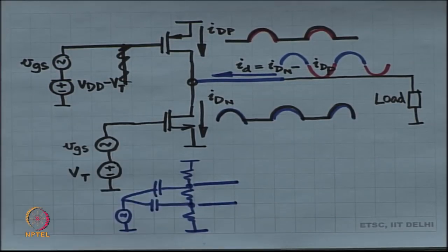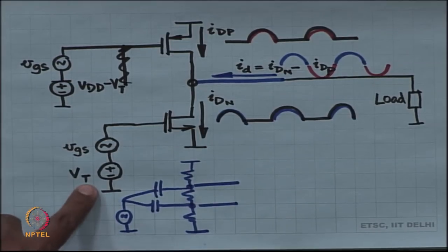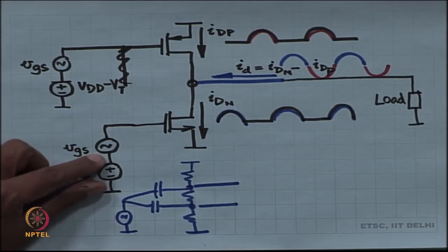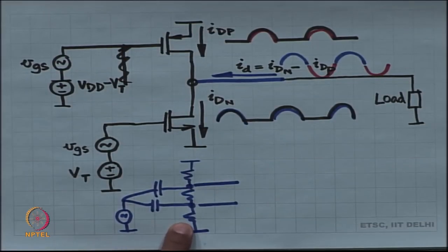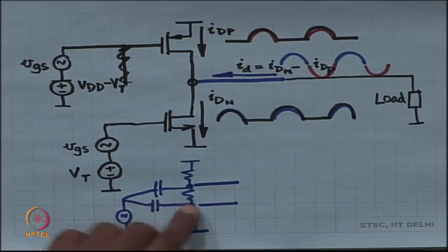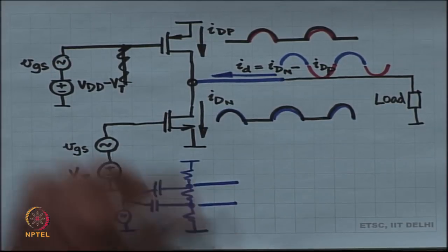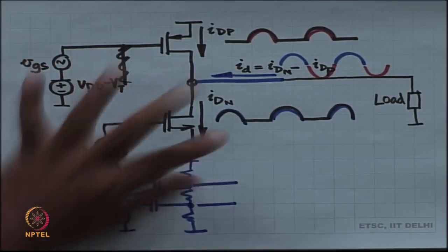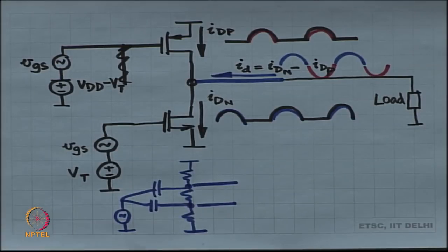Okay. You can do this through a resistive network, or through other means, but you have to be perfect. This has to be something like VT, right. Maybe you can do it through another MOSFET, which emulates a VT voltage. This should emulate a PMOS VT voltage. You can do a number of things to do that.